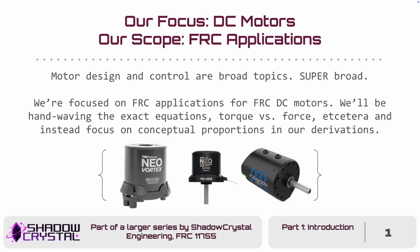So essentially that would mean your Neo Vortexes, your Neo 2.0s, your Kraken X60s, all modern FRC motors. The physics do also apply to brushed motors, for those of you who might know what a brush motor is. But in FRC, all you need to know is that the motors you use are what are called brushless outrunner DC motors. And we'll get into what that means more in a bit.